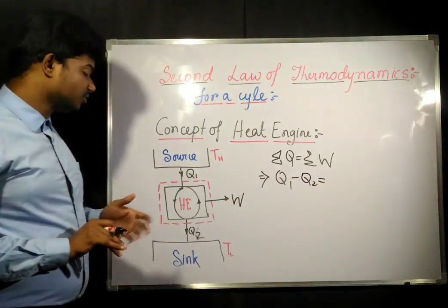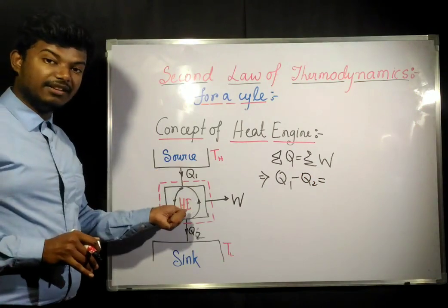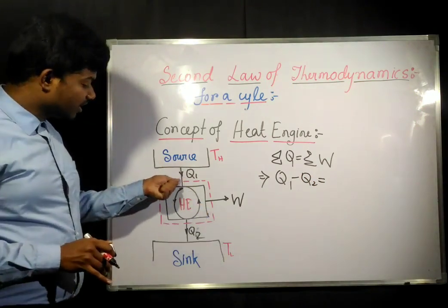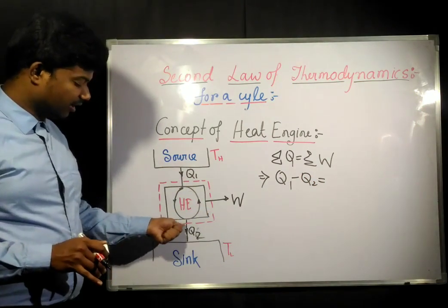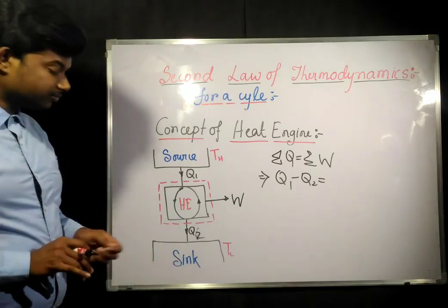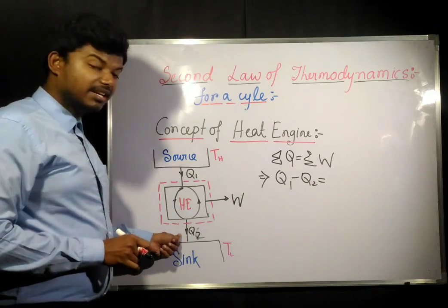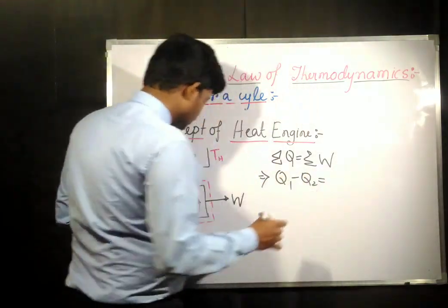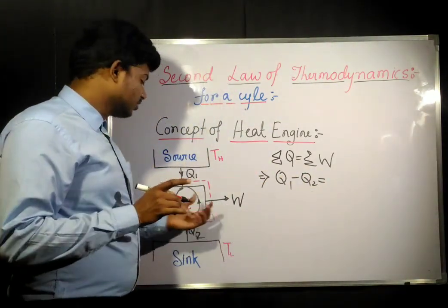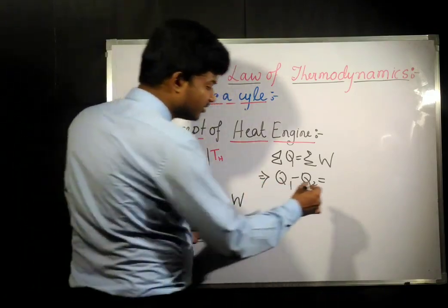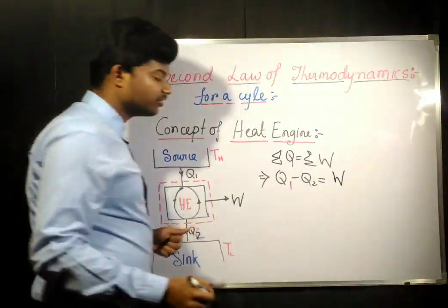According to sign convention, we have seen that our motto is to give heat and take out work. So we are giving heat, that means this is positive. Now here heat is coming out of the system, that means this is going to be negative. Now work, there is only one work, which is coming out of the system. So work coming out of the system means this is positive.